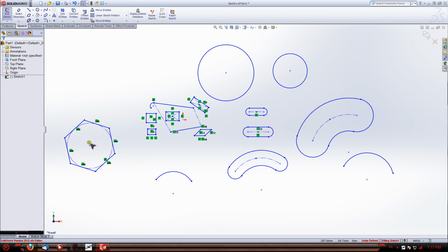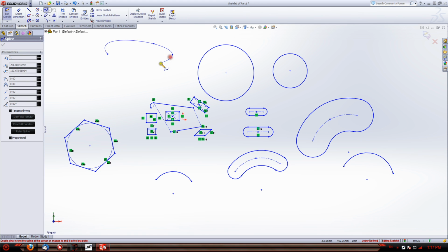It's not really crucial how you make it, because if you do to the outside of the circle, your edge is just going to be the radius. If you do inside the circle, your point will be the radius. Just depends on how you want to dimension it. Then you've got the spline tool. Spline basically just adds a bunch of curves that are always tangent to one another.